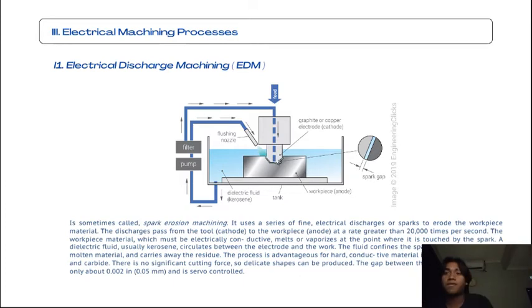The rate of cutting and surface finish are controllable by varying the frequency, voltage, and current in the electrical pulses. High energy levels in the pulses produce faster erosion of the workpiece but a rougher surface finish. Typically, the rate of cutting is reduced towards the end of the operation in order to provide a smoother surface. Spark erosion produces small craters in the workpiece, and these craters are manifested as a matte finish on the workpiece.